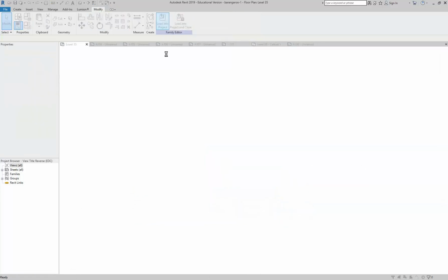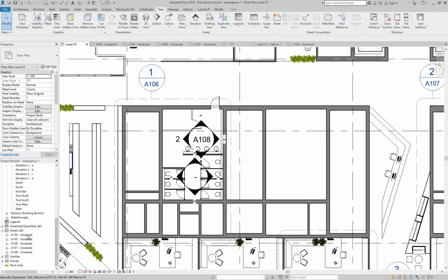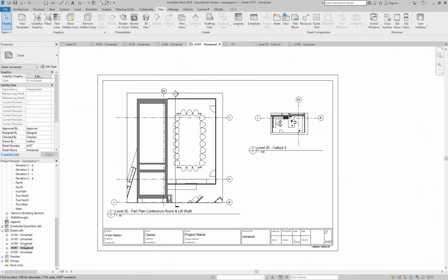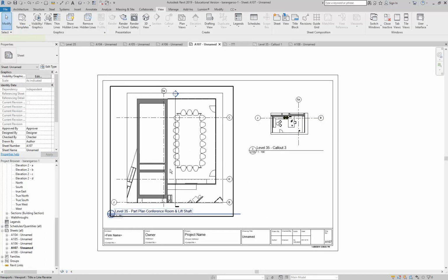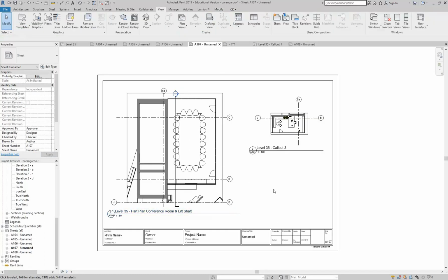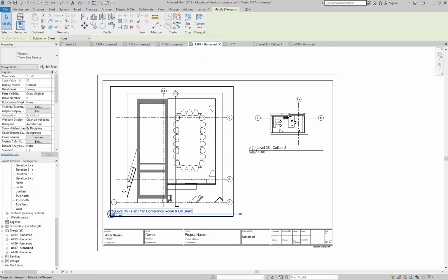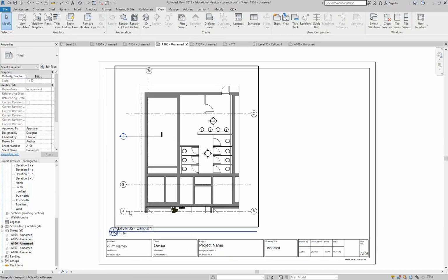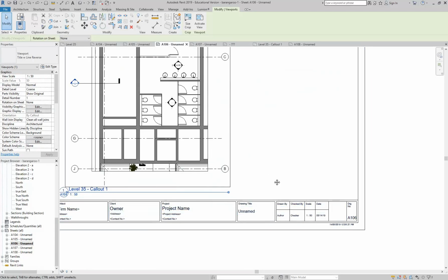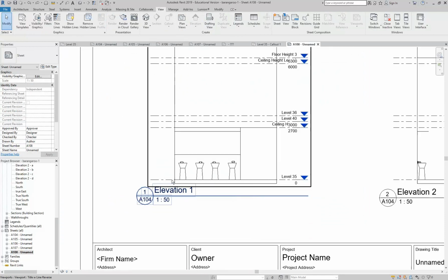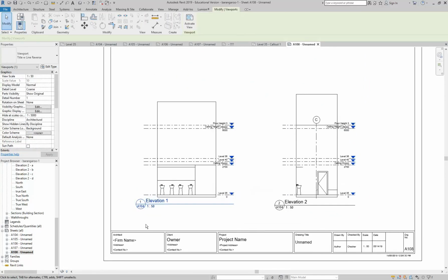Let's just load that back in. No, that's not going to work either. Okay, so Revit, unfortunately, when it's multiple, it doesn't like that. Yeah. But you should have a choice, because it's going from the call-out. Yeah, okay, that's a programming error, well, an issue with the way it's programmed. Yeah, so there, it's definitely on A106, but it's picking up A104, so that's a shame.